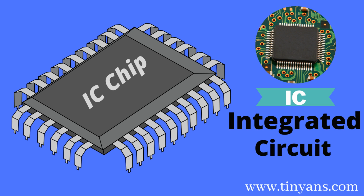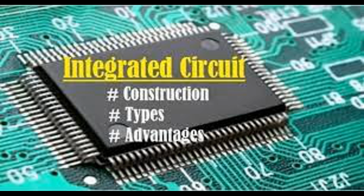These circuits incorporate memory elements, typically flip-flops or latches, to store information and enable sequential behavior. Here are the key aspects of sequential logic. Memory elements. The fundamental building blocks of sequential logic circuits are memory elements. The most commonly used memory elements are flip-flops and latches. These components store binary information, 0 or 1, and can hold this information over time.